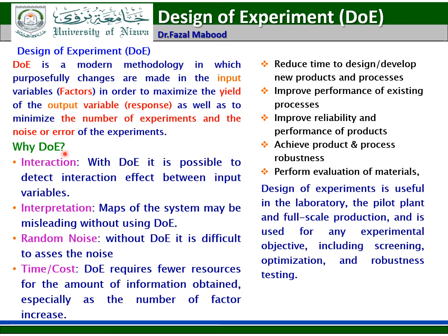Why design of experiment? Interaction. With design of experiment, it is possible to detect interaction effects between the input variables. Interpretation. A map of the system may be misleading without using design of experiment. Random noise. Without DOE, it is difficult to assess the noise. Time, cost. DOE requires fewer resources for the amount of information obtained, especially as the number of factors increases.